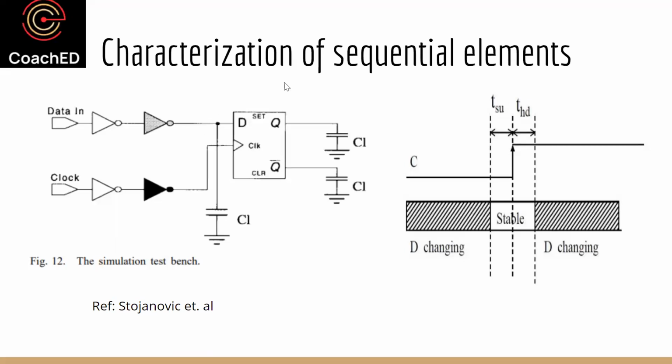There will be an input to output arc, which means like a clock to Q, clock to out, or a data to Q or data to out. But additionally, since there is a sequencing requirement between data and the clock, they need to arrive in specific order and at a specific separation, which means there's also an arc between these two. That is a special property of sequential elements. So setup and hold are basically input side arcs of the data with respect to the clock.